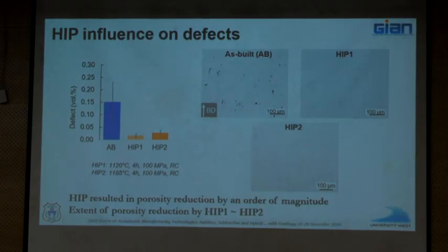But that HIPping process is secondary. The first, the material should be clean or stronger. Why? You are doing HIPping, all the thermal treatment you are doing, so that you eventually get mechanical properties that are of interest to you. You don't care what your as-built thing looks like, right? That's the reason you want to post treat.